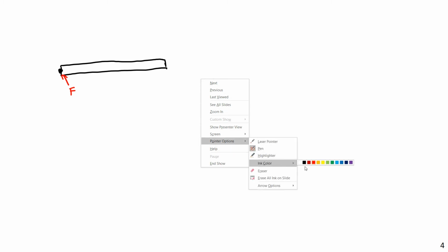When you apply a force to a door, like on its handle, maybe I can actually sort of draw that. The door's handle would be here or here. When you apply a force here, you have a large moment that you're generating, and that force goes to move the door. But there is still a minimum amount of force required. It's not like you can apply a very, very tiny force and then just have the door slowly accelerate. There is going to be a minimum amount of force needed to open the door, and that comes from the internal friction in the hinge.